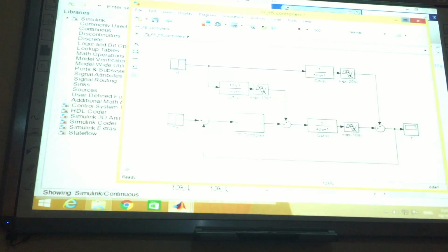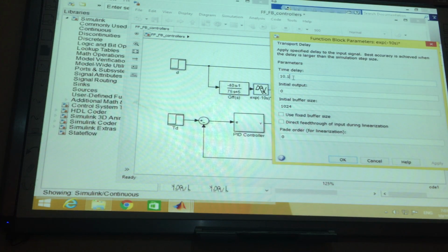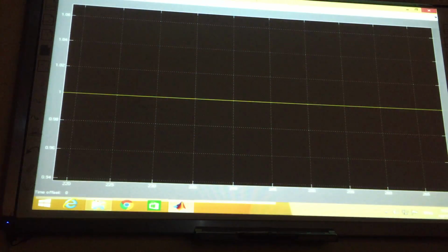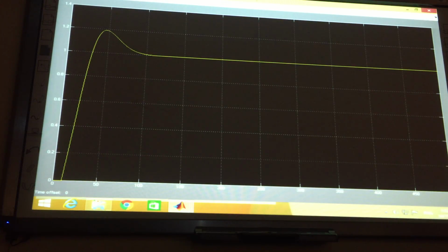Okay. This is transport delay. The transport delay, we found it, it's minus 10, right? Yeah, it should be minus 10 seconds. If you have a very accurate sensor that gives you that exact value with no delay, then the system will get rid of the measured disturbance, as you can see. Is it clear now?